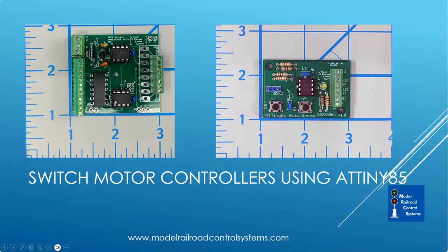So we built one with an ATtiny, which is a little Arduino. And what's cool about it is that it senses when the servo is facing resistance and turns itself off automatically. So it's self-calibrating, and with servos, particularly the inexpensive SG90s, they tend to wear over time and the resistance changes a little bit, and periodically you need to recalibrate them. So this one kind of gets around that. Anyway, a very sharp guy named Lawrence Kroll has been working on that, and I expect to have it later this year.